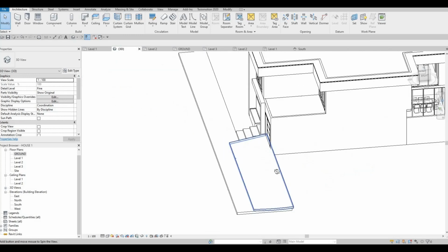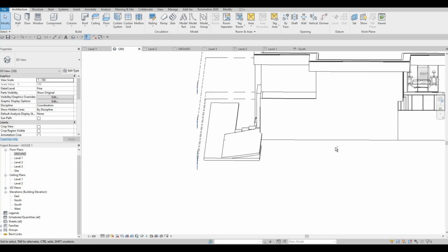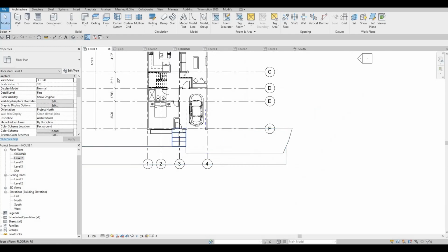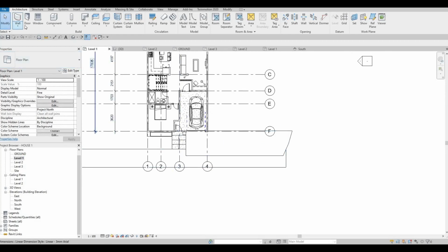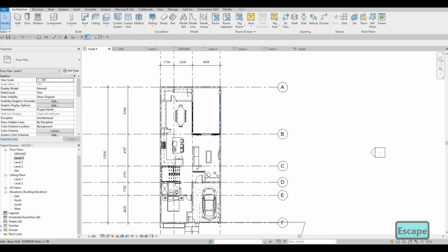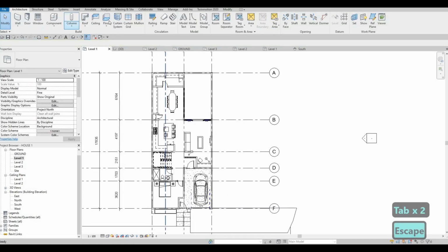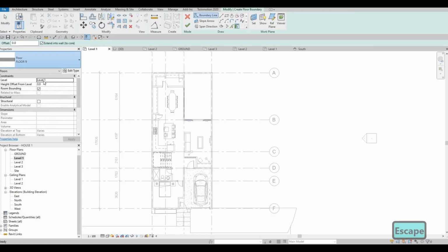We just need to add a floor right there from the level 1. That will be grassed. So click on, we could add this floor. This is floor number 4. So click floor, look for floor number 4.